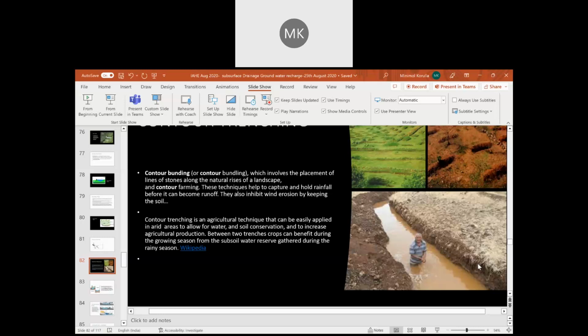Now whether the front fascia is free draining and the chimney drain, is it enough? No. From the chimney drain, there should be a path which will be taking the water out. And in this case, I don't know whether it is visible to you, an inclined pipe is connecting the chimney drain to the outside. Okay.